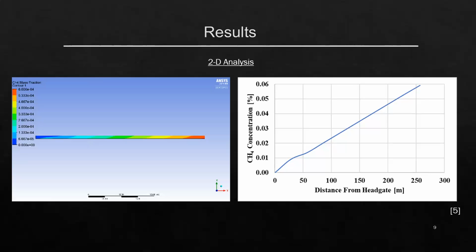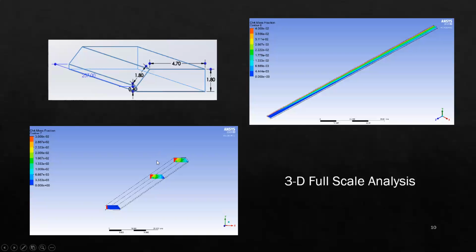I did have some issues at first, because this is really my first full attempt at doing CFD stuff like this. So I had some issues with things converging and solutions running away with the grid or the meshing. Once I seemed to fix those issues, I refined the mesh a little bit. Then I finally started to get these, what appear to be, more accurate profiles. And I still had some issues with the 3D stuff, one of which is just a timing issue. I didn't have much time to work on this yet from the stuff that I'm presenting here.